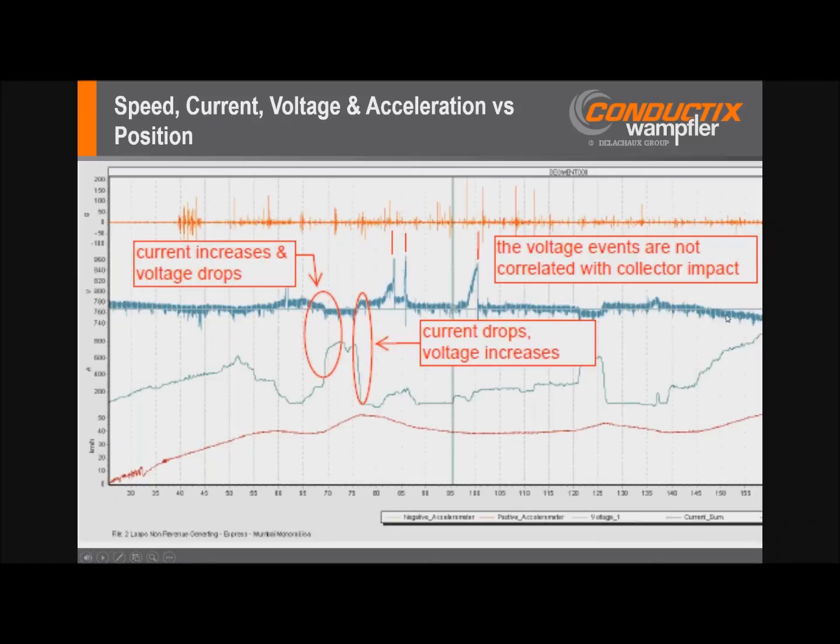By simultaneously recording the substation power conditions, current and voltage, and time syncing that with the vehicle, we can determine how much voltage variation is due to the guideway or the power rail, how much of it varies with the current demand of the vehicle, and also identify if there are power supply issues, maybe with the substation or the grid connection, that may be contributing as well.